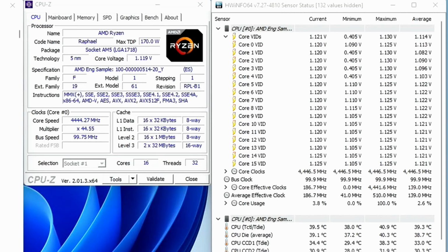The public tools and public BIOSes currently only support up to -30 steps, so it's a little bit difficult to illustrate how it works. But using non-public tools, I was able to gather some data that hopefully helps you understand what's going on. The approach is straightforward. I record the actual voltage and effective clock frequency during a workload as I adjust the curve optimizer setting.